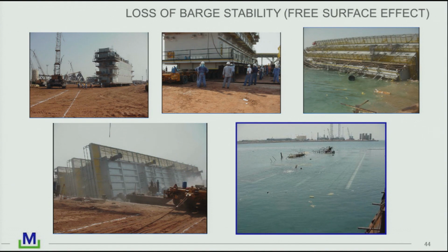The free surface effect during loadouts, as I mentioned right at the beginning, is a real issue because the people dealing with this, you might not have a naval architect at the forefront of this. Probably he or she's done calculations a month or two before, but the operation is done by people who don't understand that free surface effect. Somebody's just ballasted the barge to get it level and then not worried about the fact that each tank is half full. Well, naval architects are very expensive.